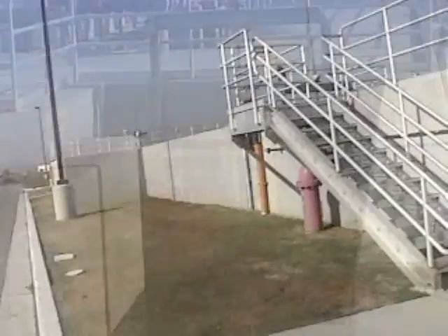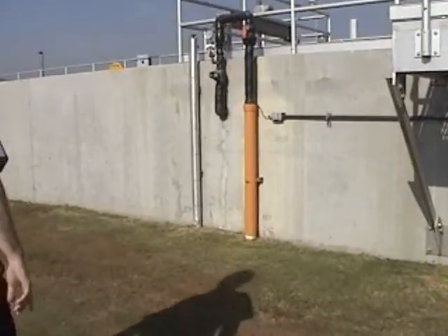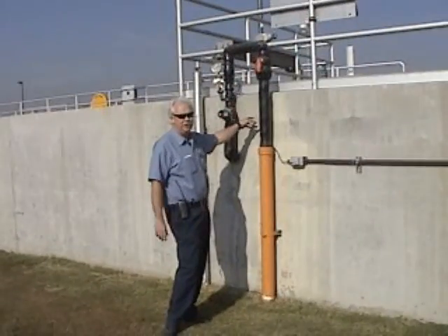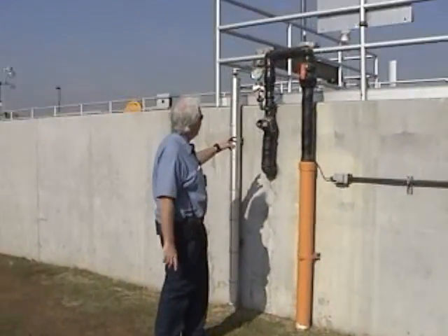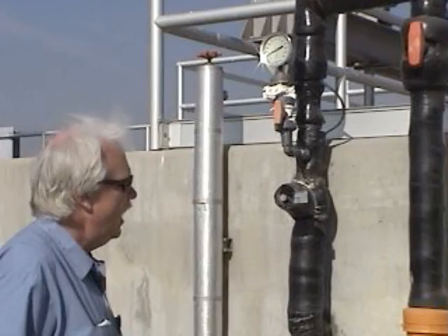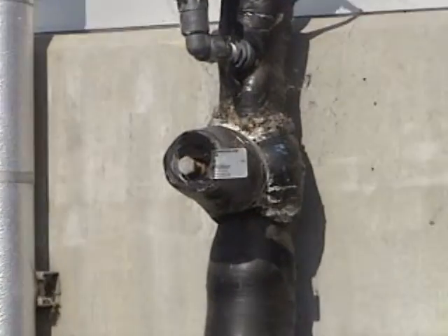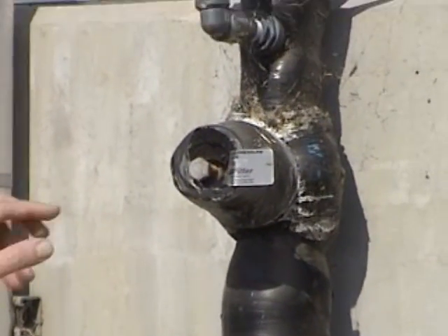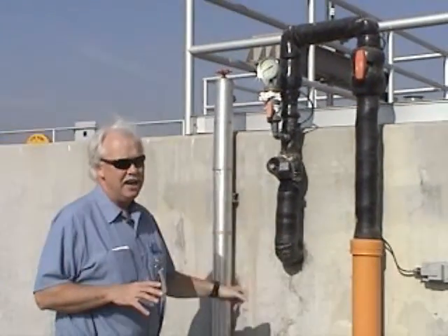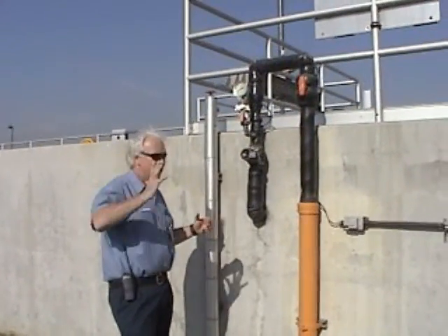So this orange pipe coming up the wall is the sodium bisulfite line. It provides sodium bisulfite for dechlorinating the effluent. It's important: this is a backflow device right here, and it puts back pressure on the system. We have a problem here because the pumps are located very far away, so the response time was rather low. By putting this backflow device on it, it puts back pressure on the pump so that the line between here where we discharge and where the pumps are located is constantly pressurized, and so when a gallon goes in, a gallon comes out the other side.